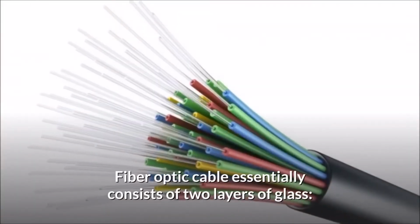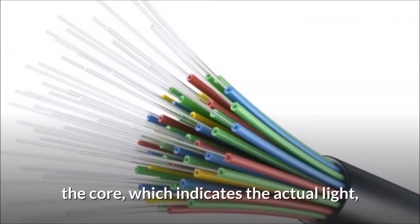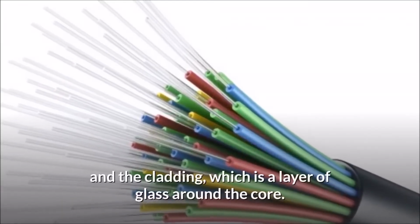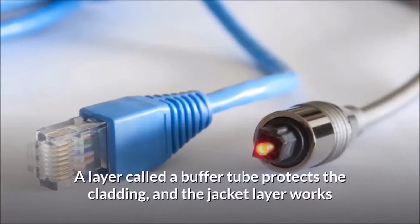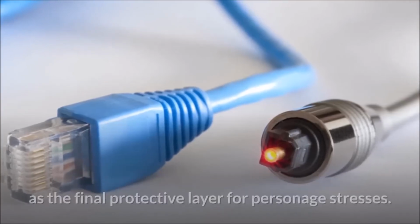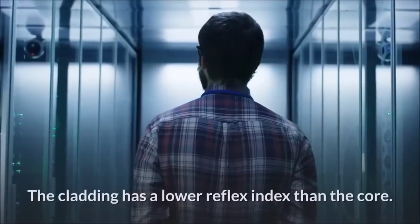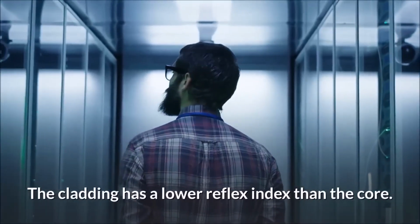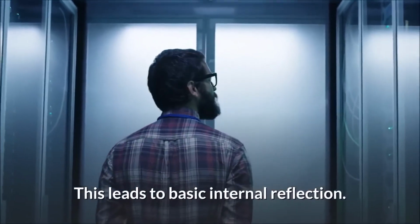Fiber optic cable essentially consists of two layers of glass: the core, which carries the actual light, and the cladding, which is a layer of glass around the core. A layer called a buffer tube protects the cladding, and the jacket layer works as the final protective layer for individual stresses. The cladding has a lower refractive index than the core. This leads to total internal reflection.